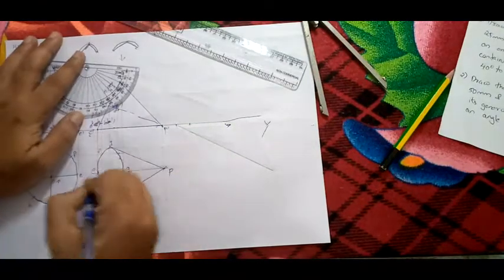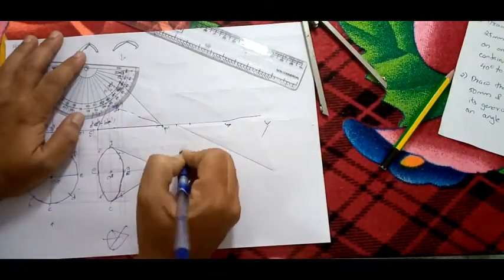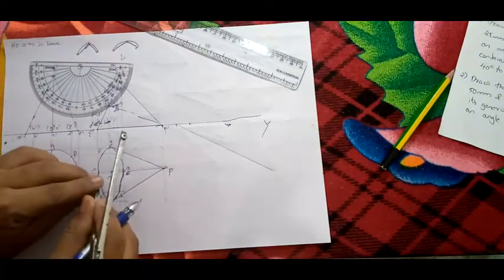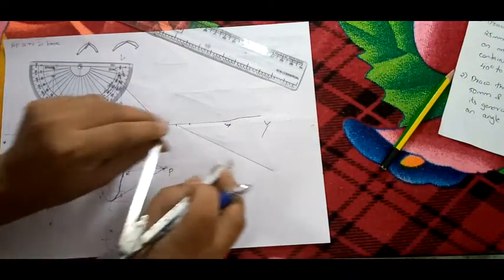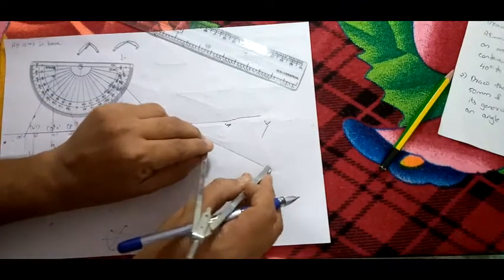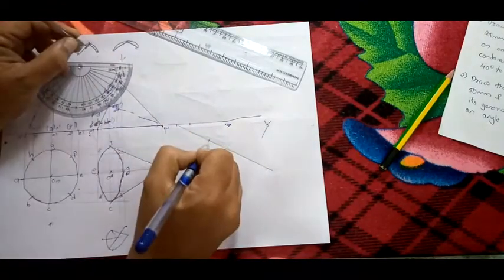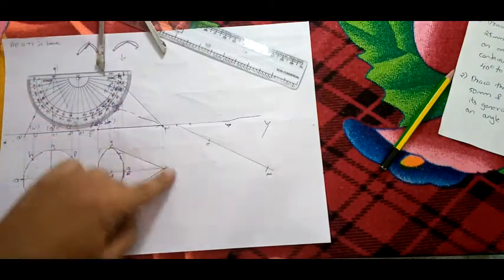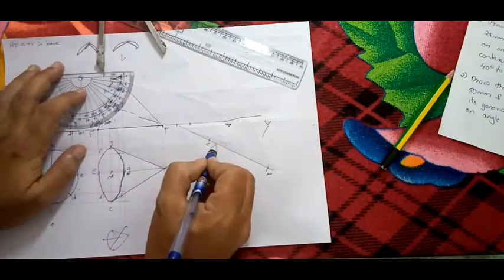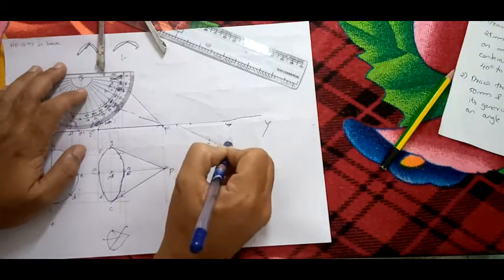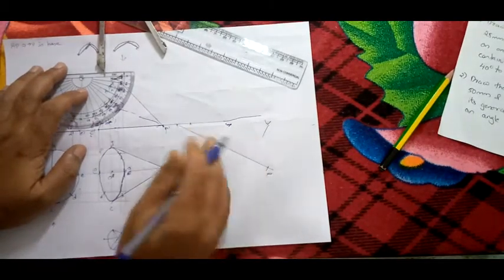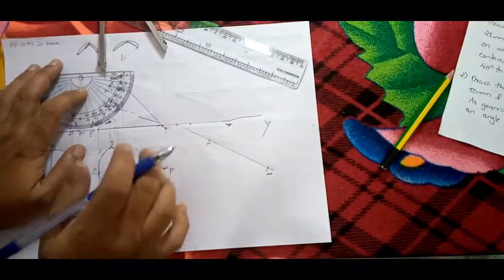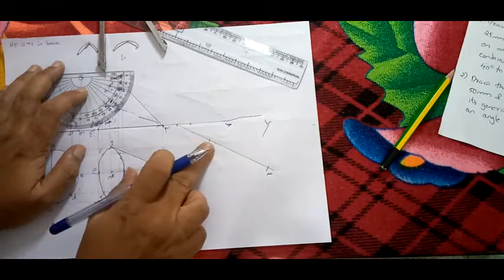I will be drawing E dash P dash, EP. First we will start with the EP like this. You have to mark it like this. EP. See, this much distance I have taken. Why? In order to accommodate this. If you find your next points like this, the ellipse should be here, right? This ellipse should be here. If you are drawing here, this ellipse should cross the XY line. For avoiding that, I have taken E somewhat below.